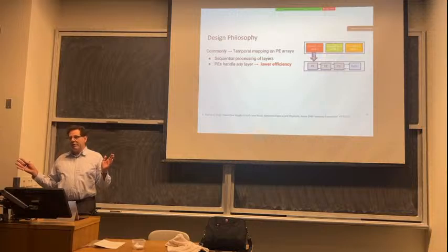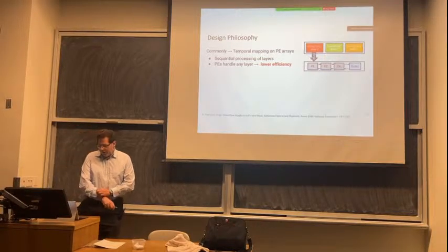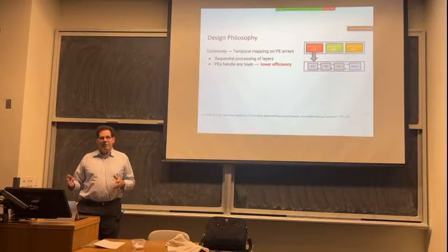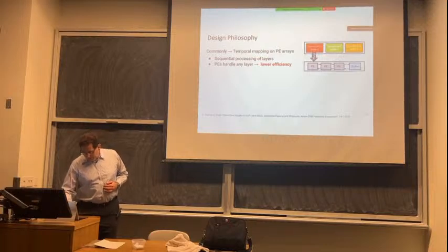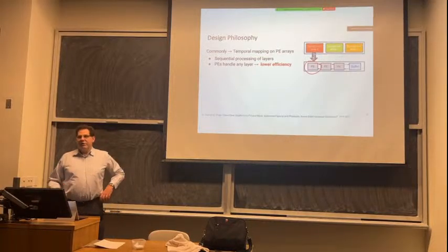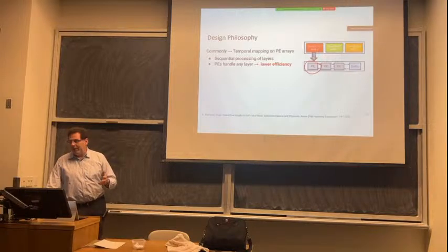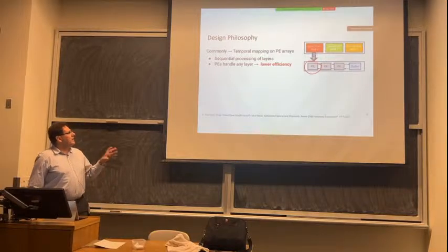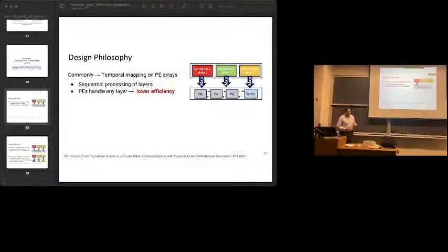Typically used for things like image processing and object detection and so on. There are a couple of different ways you can build an accelerator for a convolutional neural network on FPGAs. One is that you could make some kind of generic processing element. It's got some multipliers, some adders, and some muxing to allow you to move data around, etc. It's relatively generic, and you can use it for all of your layers.